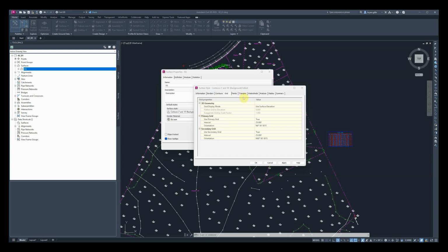And here I think it's important to note on the subject of grids: they are essentially Cartesian coordinate systems that store your elevations as properties versus actual values. In relation to GIS, grid would be similar to something like a raster, where we have our rows and columns, with stored values that we then visualize as a Z, versus a tin surface or actual 3D model or a point cloud.